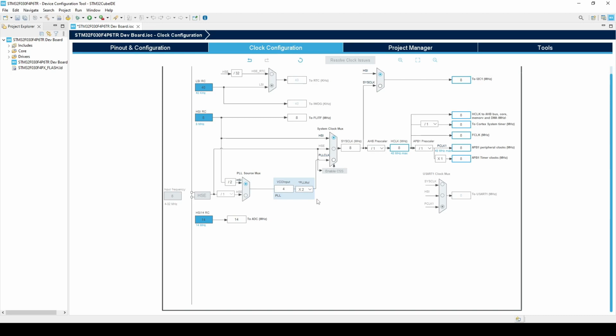This means you receive the clock system, which provides clock to the AHB bus, and this prescaler takes values from 1 up to 512. So look: 1, 2, 4, 8, 16, 512. These are set values, and you'll see on the datasheet when you're looking to program, you'll see each of our ports and whatever has a bus related to it.